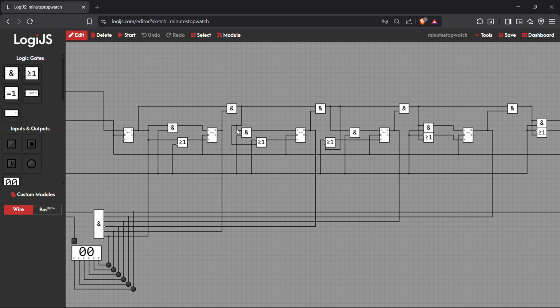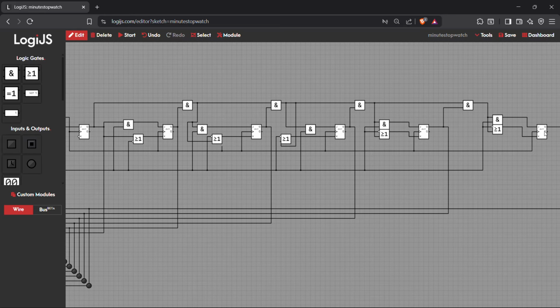After ending this, the result will further be ANDed with the not reset and ORed with the reset and passed to the J and K respectively of flip-flop number 3, or let's say flip-flop number 2 according to one naming scheme. This will again be ANDed with the previous such that when the previous three are enabled, then only will it be passed on to the fourth JK flip-flop. So in this way we are cascading all the signals such that the last JK flip-flop will only be triggered if and only if all the previous JK flip-flops are triggered.